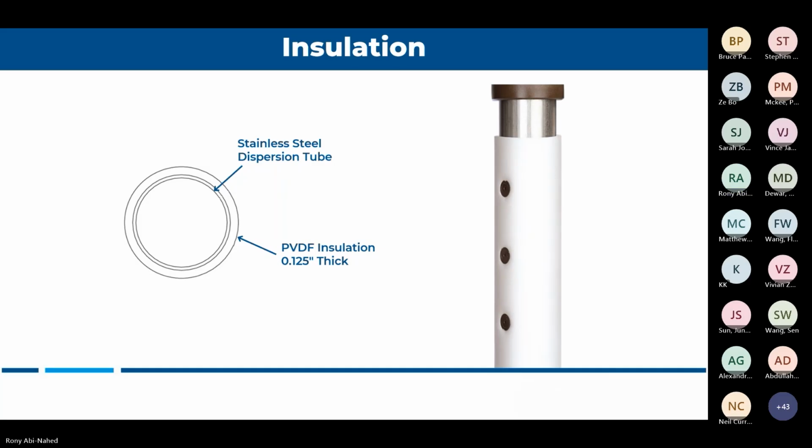So for me, if I want really to give advice, when you're speccing an insulated grid, I always recommend you pick a brand that has a double wall stainless steel, or they are protecting their insulation with stainless steel. And there's a bunch of them. So, it's not just one brand that it will be like a spec stopper. There's a bunch of them.